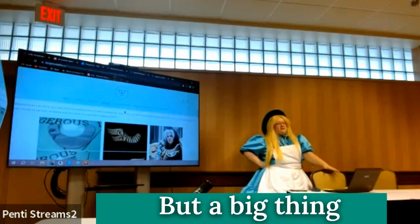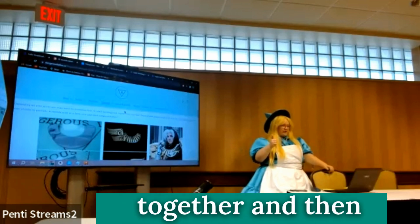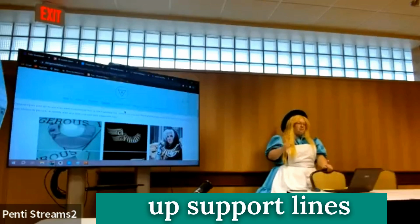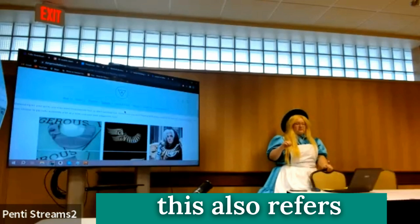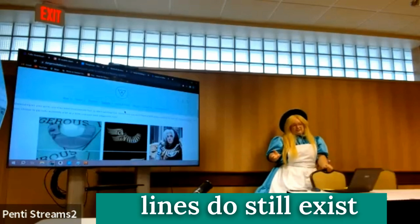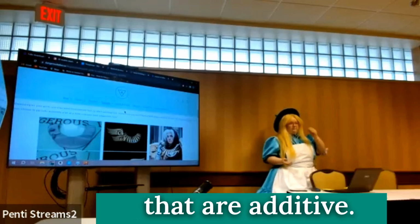But a big thing is that whenever you're working on your finishing, you have two main things that you're going to want to do. Stick the parts together and then clean up support lines and layer lines. It's important to note that part of this also refers to resin printing, because even though the layer lines are a lot less noticeable, layer lines do still exist in resin printing, just due to the fact that inherently these are methods that are additive.